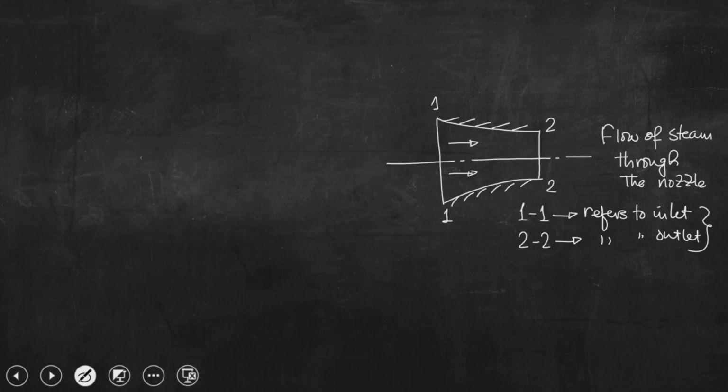By applying the steady flow energy equation, we could write C dC plus dH equal to 0, right. So, this is equation number 1, that is what we had written in the last class as well, and this equation is obtained from the steady flow energy equation applied between these two sections, section 1 and section 2.